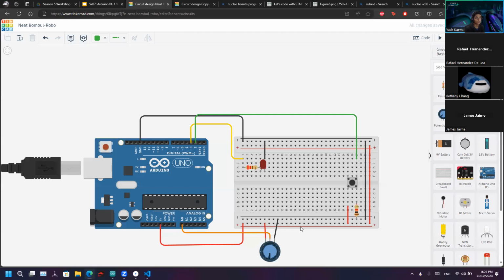One more time. What's happening here in the code is that there are so many delays right now. Whenever you press the button, the Arduino is probably on its delay, where it doesn't read anything. It halts everything for a certain amount of time, so it's not reading when you press the button because the delay is kind of big. So lessen your potentiometer so it blinks fast at a dimmer state, or just to 0. Then you can press the button again and it should be fine.